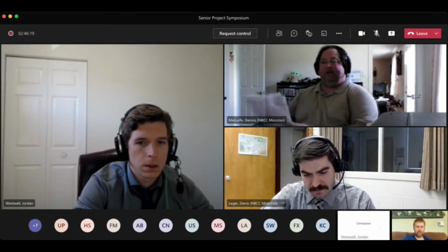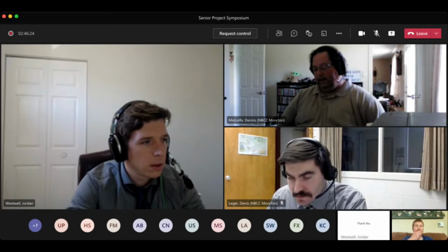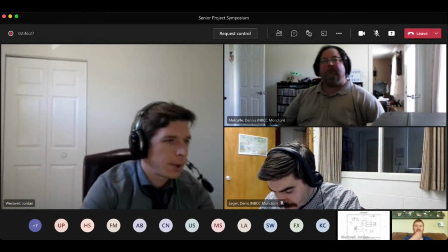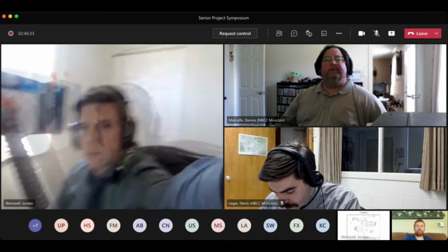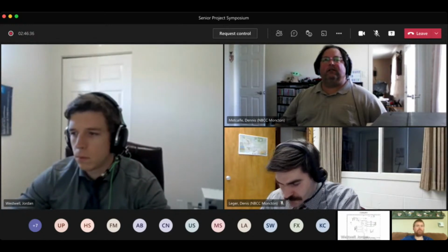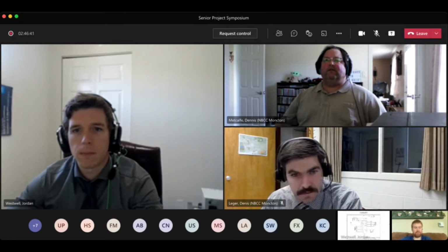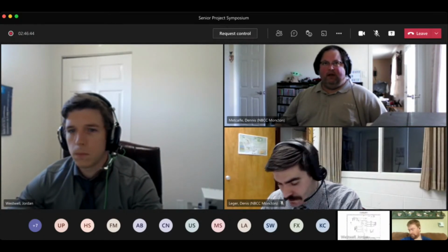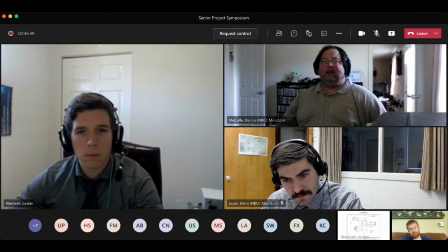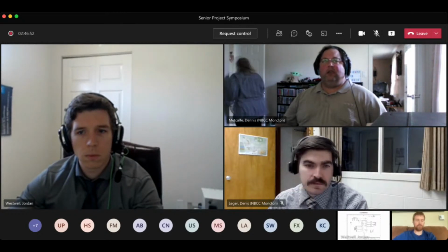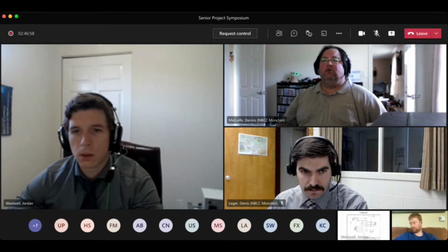Could you bring up your schematic for a second? Yes. Hold on. Excuse me. There we go. I was just curious. I would personally find it somewhat difficult if I had to work on your device based on the schematic, due to the fact that you show your headers and all your connectors, which is great. I love the fact you have that, but you don't show what they're connected to.